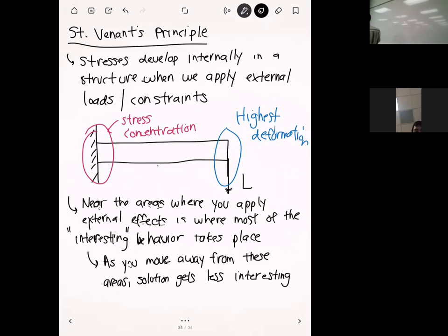What you should see is that it is not exact, but when you halve the element size, you end up with about 4 times the number of elements, because it's a squared relationship. Something's wrong with my calculations, I got about 3 times. Yeah, it's going to be somewhere in between; 4 is kind of the upper bound. I got 3.68. Yeah, it's going to be closer to 4 rather than 2. Okay, all right, thank you.